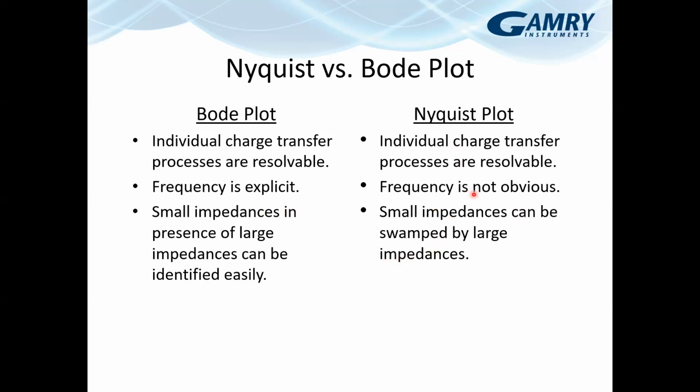Frequency is not obvious. That said, a lot of times things are easier to resolve in the Nyquist plot than they are in the Bode, where individual processes tend to blend together a little bit more. So it's often easier to resolve multiple processes in the Nyquist plot.